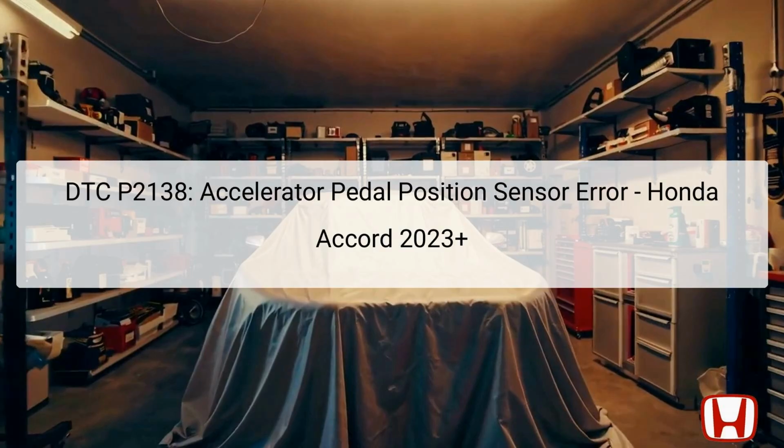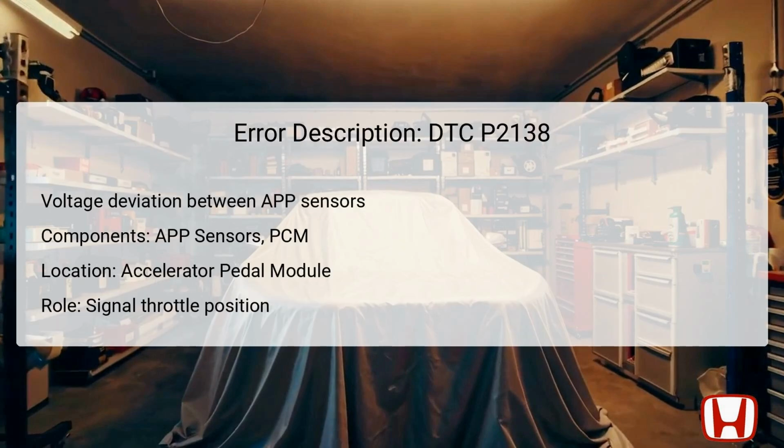Given that this diagnostic issue involves specific components, understanding their roles and locations is vital for accurate troubleshooting. The core issue, described by DTC P2138, revolves around a voltage deviation between the two APP sensors. These sensors are integrated into the accelerator pedal module, which is typically located on the vehicle's floor near the accelerator pedal.